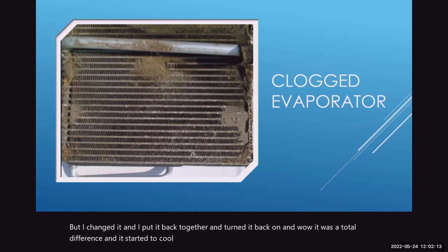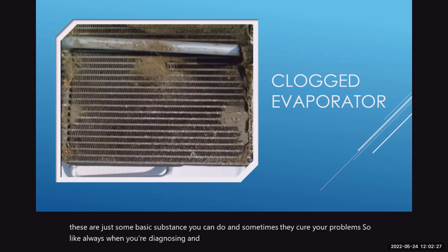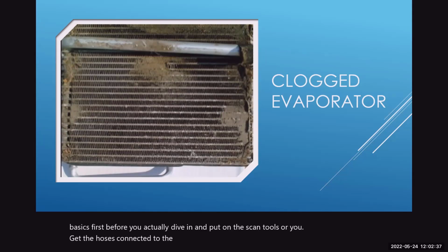I did have to kind of garden hose the condenser too, but these are just some basic steps that you can do, and sometimes they cure your problem. So like always, when you're diagnosing and you're looking at things, always try to go for the basics first before you actually dive in and put on the scan tools or actually get the hoses connected to the system. You want to look over the basics first before you go to the next step.